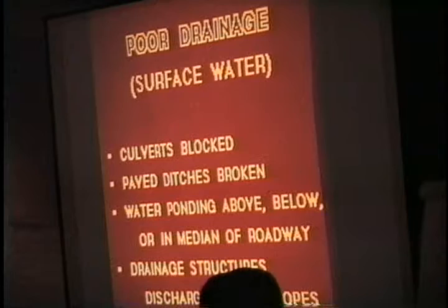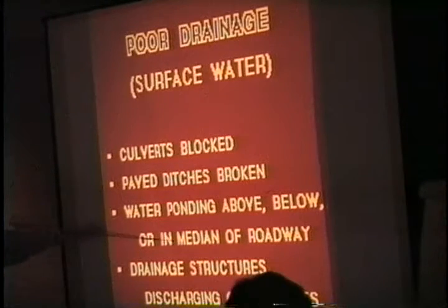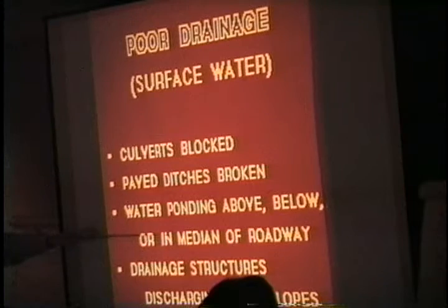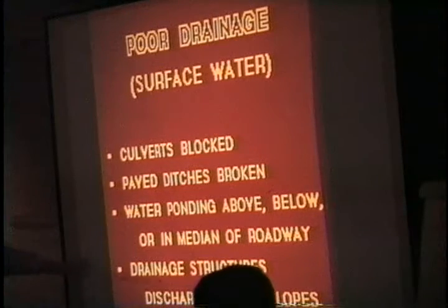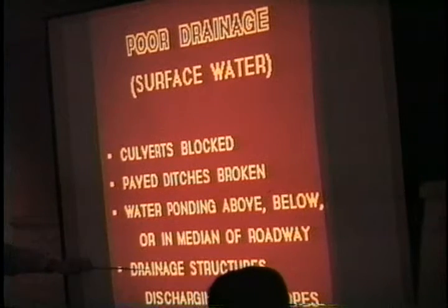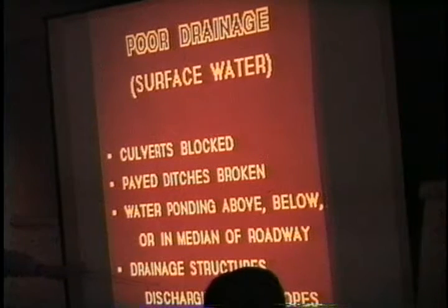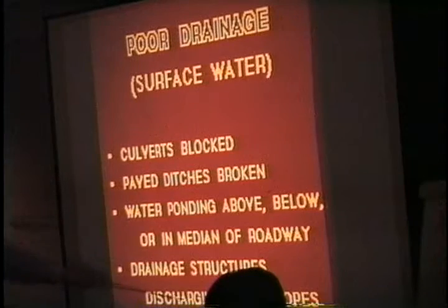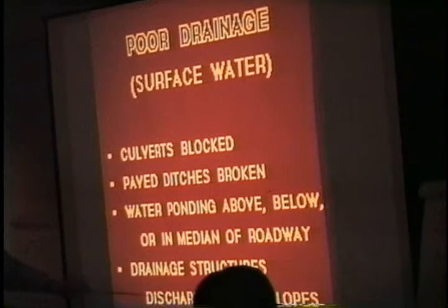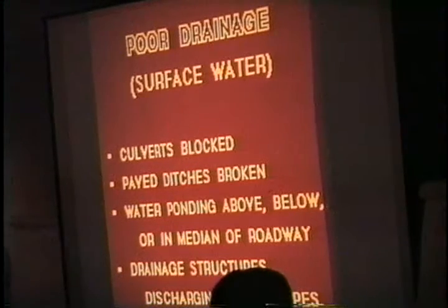Okay, poor drainage, surface water, culverts blocked, paved ditches broken, we mentioned that. Water ponding above, below, or in the median of the road. Drainage structures. We mentioned the culverts with separations. Drainage structures discharging onto a slope. Classic one at the ends of bridges.